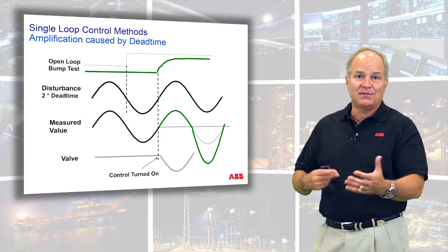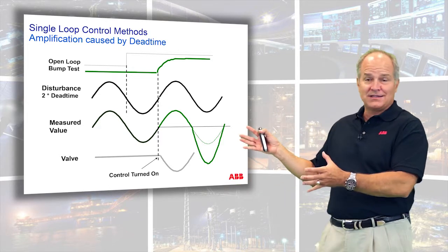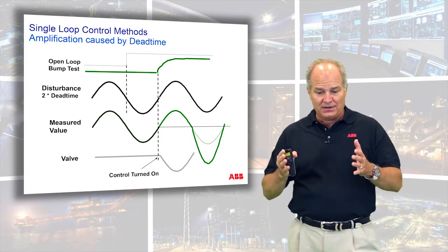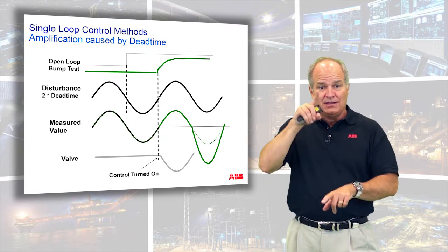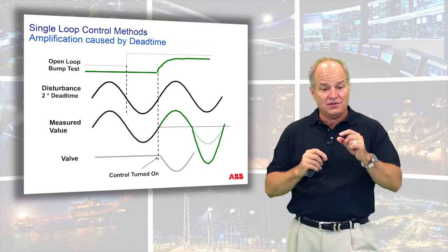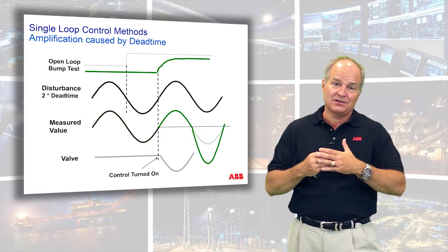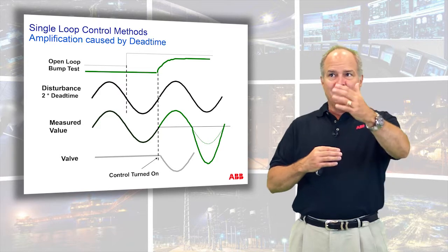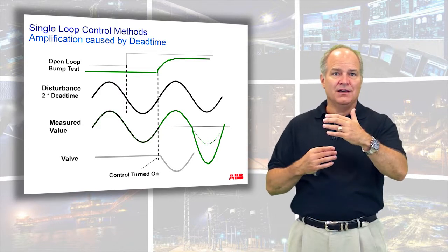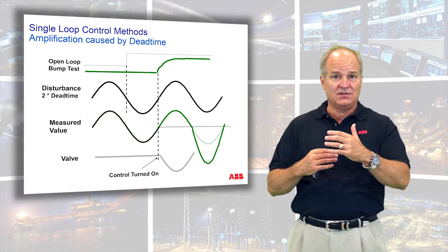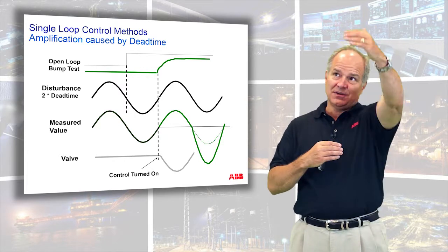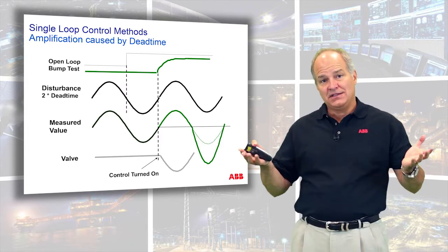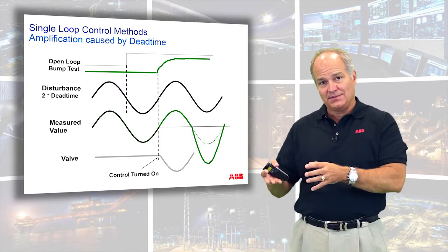So what happens is I amplify. This is as simple as I can make it, and it's not that simple, but it shows the amplification of an oscillation with a period exactly twice the dead time. You get it, and so in internal model controllers, you have to be aware of that amplification factor. One nice thing about dead time compensators is you can limit it to, I think, 2 or 3 times the amplitude based on aggressiveness of tuning, whereas with a PID algorithm you could jump up to 50 or 100 times. So you can stabilize these disturbances greatly with a dead time compensator.